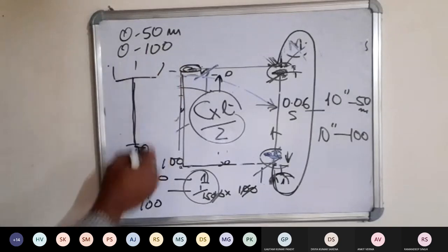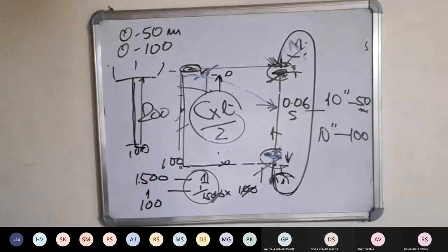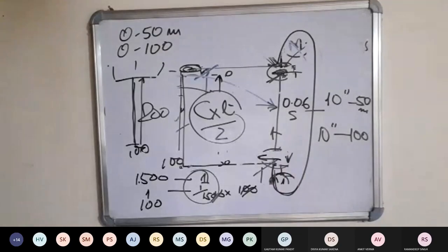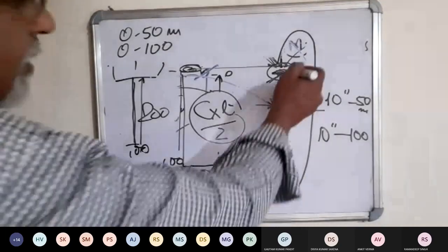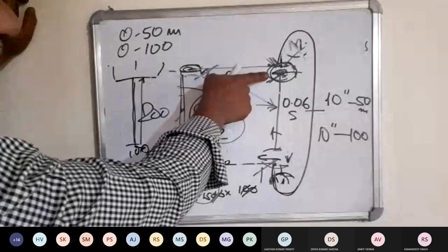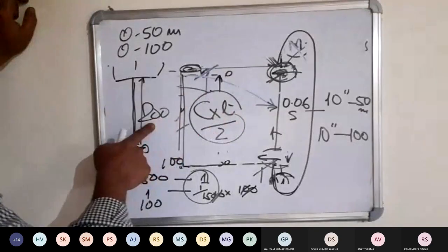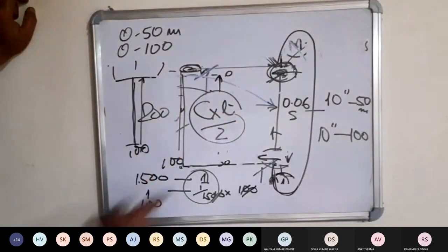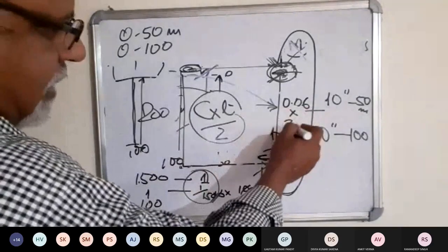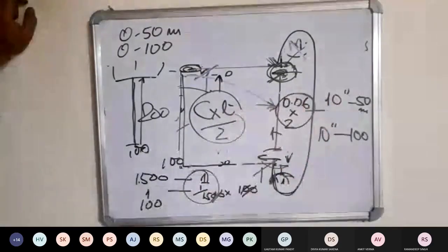Now suppose that you are measuring, let us say, 100 meters. That means the signal will go and come back, 200 meters will be the travel, and the marking should again be at the bottom here itself. That means this time the stylus takes the time which is required for 200 meters at this speed to travel. That means will it be twice the time or not? Yes, sir.